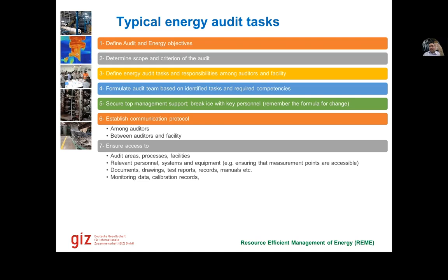If we want to do a stack analysis, ensure already that there are points available there for inserting the probe. If you want to do flow measurements, ensure that you are able to install your meter there. Then gathering the documents. So if a factory is hiding drawings, hiding test reports, hiding reports and records and manuals, it is very, very difficult to move forward with this factory. And this is the point we need to talk with top management very specifically, that we cannot move forward without this data. And calibration records and monitoring data is also required.